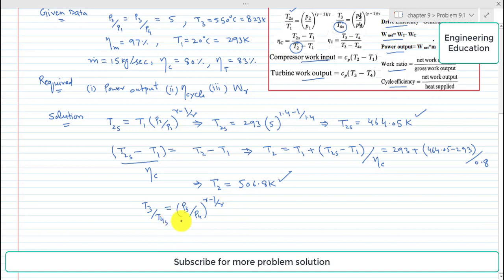Now I am interested to find the value of T4S, so rearranging the expression, T4S is equal to T3 divided by P3 by P4 power gamma minus 1 by gamma.